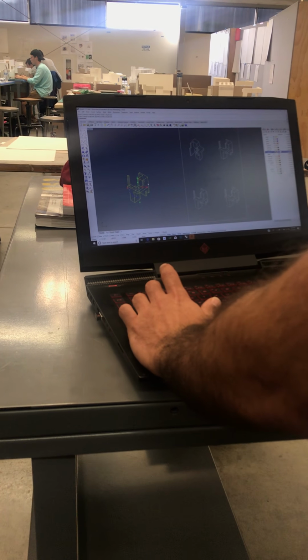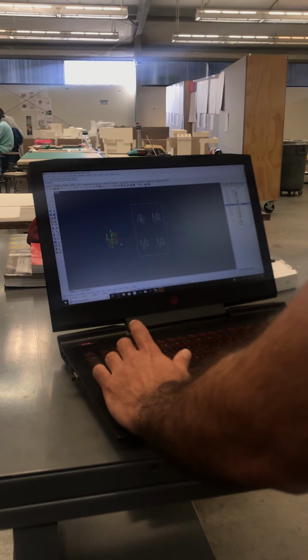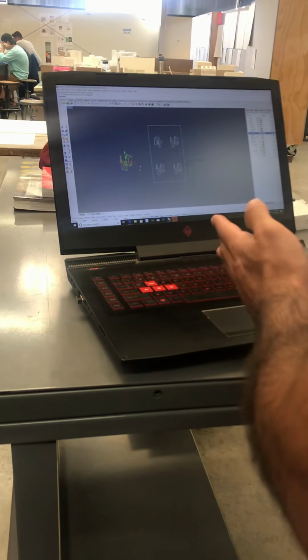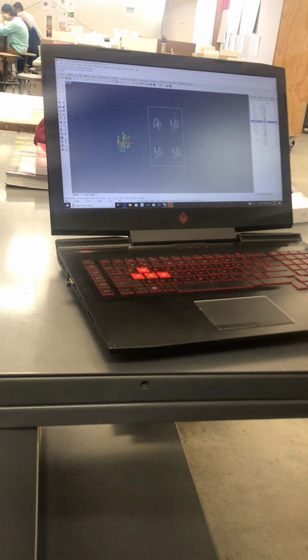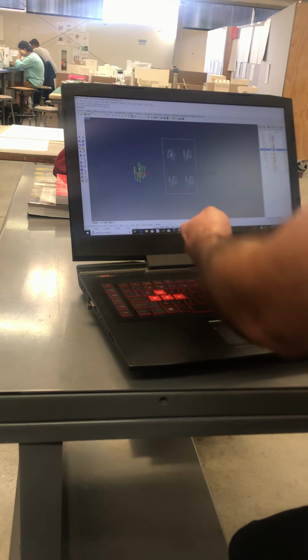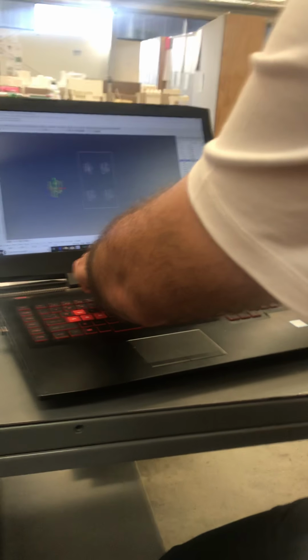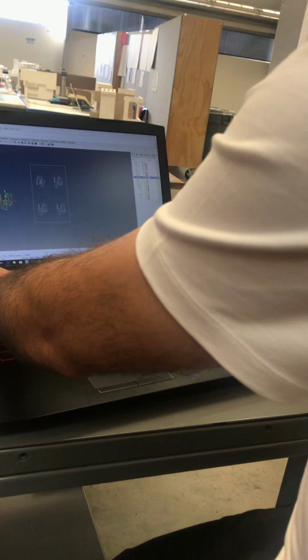And then to keep everything aligned, you use something called snap, or is that what it's called? Or you were saying snapping certain things on it? Yeah, snapping is just a concept of if I want to snap the edge of this mouse to the edge of this table, I would move it there. You can use this tool called OSnap, which stands for Object Snap. It's down at the bottom, and if you click that on, it gives you all of these little helpers down here that you can snap to.